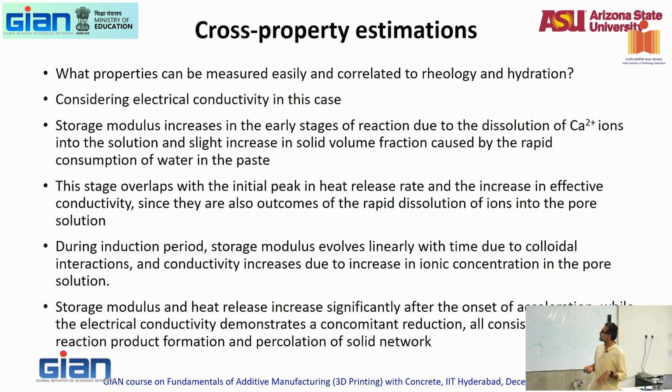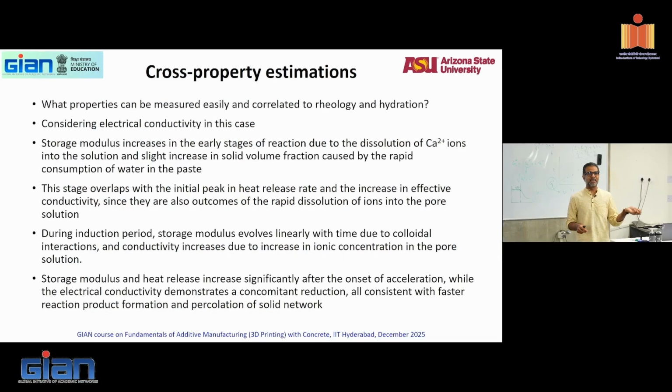What we did is went one step further and said, both these measurements are difficult. Even hydration with an isothermal calorimeter and doing all of that, and rheology, putting the paste in the rheometer, is different. Can I do something even more easily? And one of the easier measurements to make is an electrical measurement, just to measure electrical conductivity. So the question is, can electrical conductivity tell us indicators of rheology and hydration, including storage modulus?